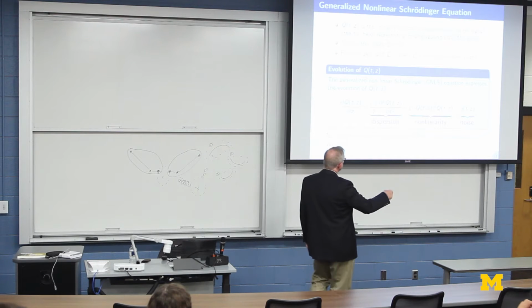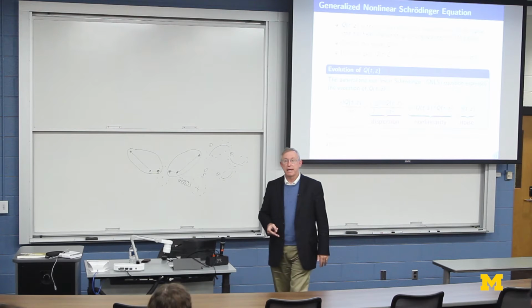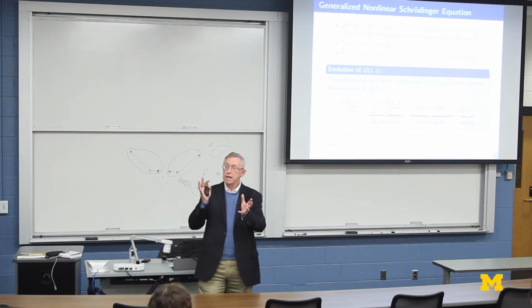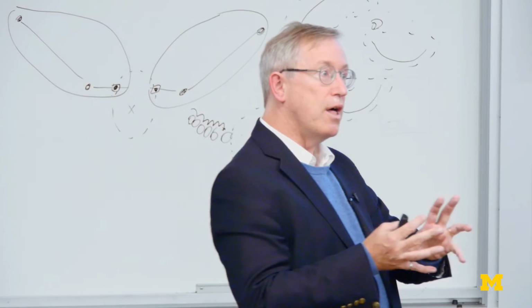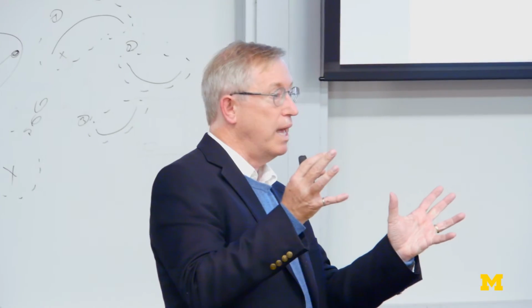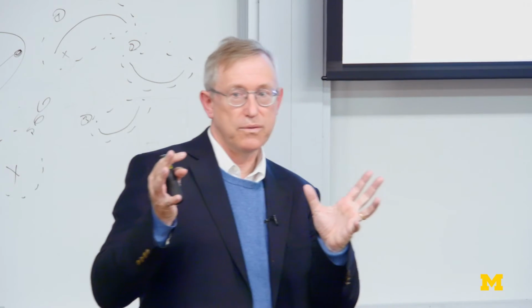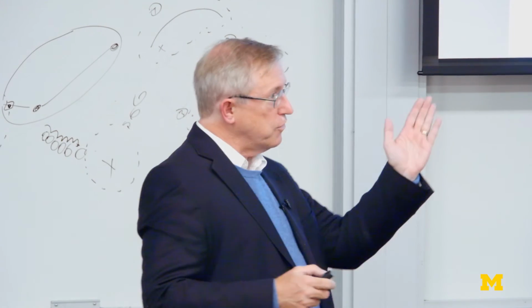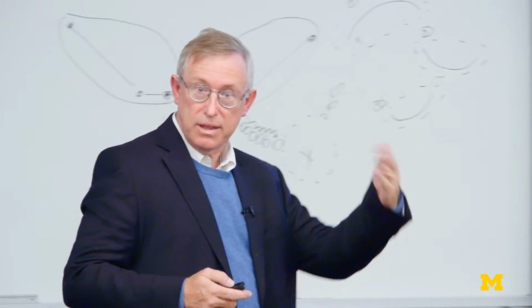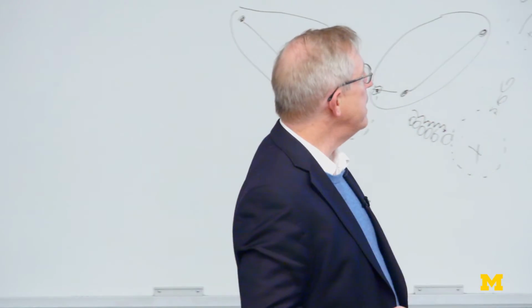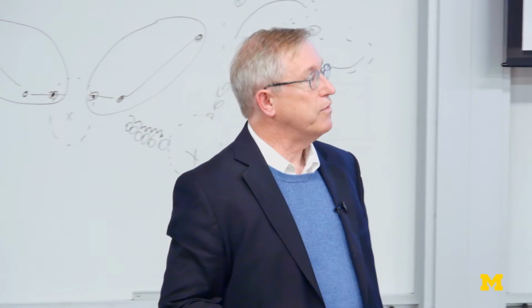And nonlinearity, this is this Kerr nonlinearity. That's going to cause changes in the phase. It's going to cause kind of a self-phase modulation of the wave as it propagates along the fiber. Okay? That's what this thing does. And that causes small changes in the angle, in the phase, as we'll also explain in a moment. And this accumulates over distance.